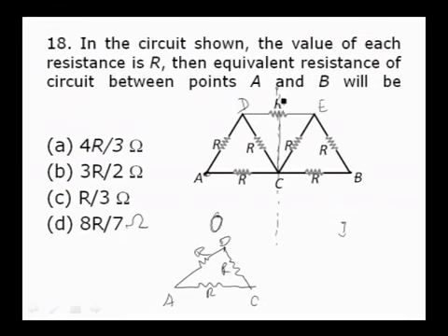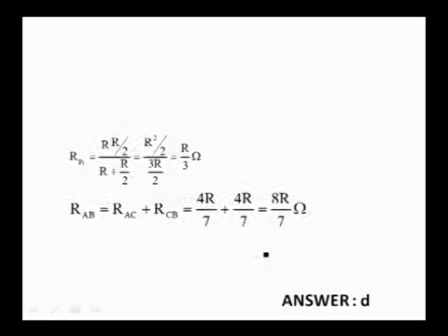See here resistance will divide equally, that is becoming R by 2, R by 2. Now the resistance between D and C, they are parallel. R and R by 2 are in parallel. You are going to calculate the parallel value of the parallel combination, that is like this. Rp1 is equal to R into R by 2 divided by R plus R by 2. If you make the simplification, you will get the value of R by 3.